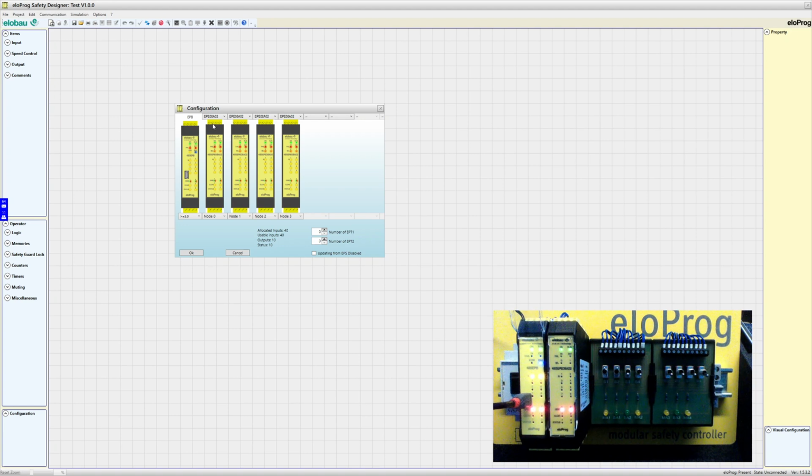And you have to choose this here in the software configuration and also wire it at the terminals. At terminal 2 and terminal 3, you have to wire 0 or 24 volt DC, depending on the node number. And you can look into the manual for the details, which potential, which voltage has to be applied here at the terminal clamps. Okay, but in my configuration, I have just one module, so I cancel the other ones and just keep this one.